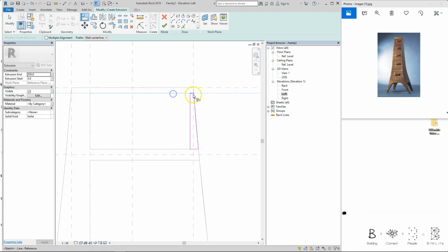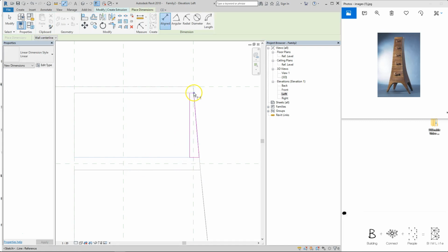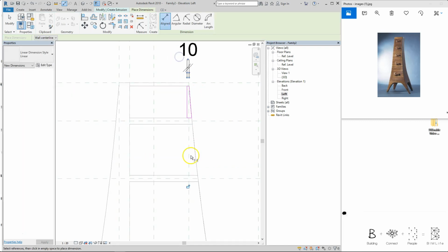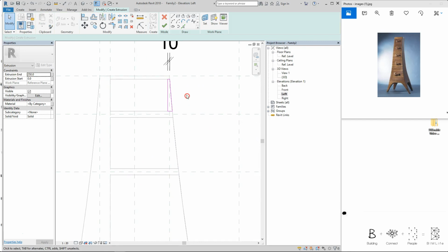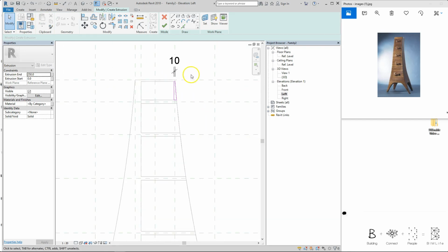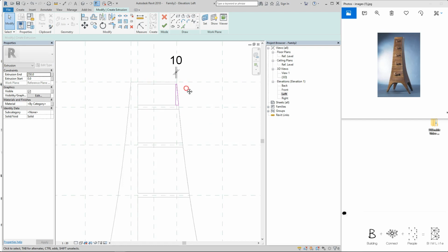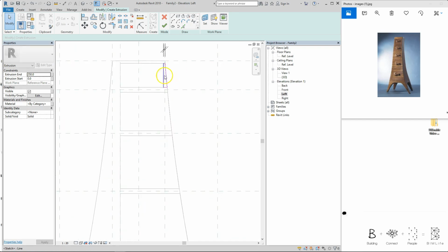I want to align my door to the sketch, or the sketch to the door actually, and then put the dimensions. Just leave it as 10 mm, make sure it's locked, so that regardless of how the height of the tower changes, I have locked them to the bottom of the first drawer and the top of the second drawer, and it will always remain, and the curvature will always adapt to the existing conditions of your cabinets.